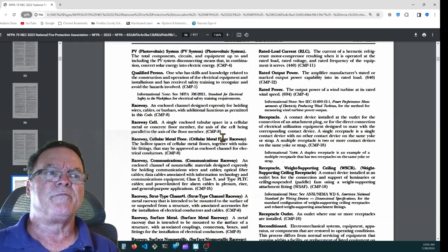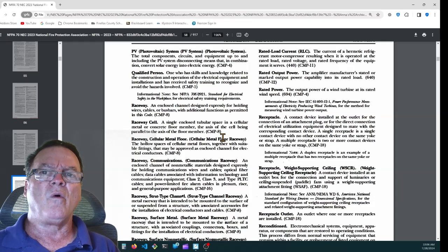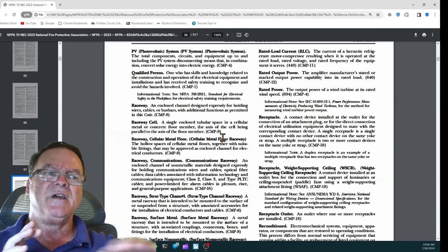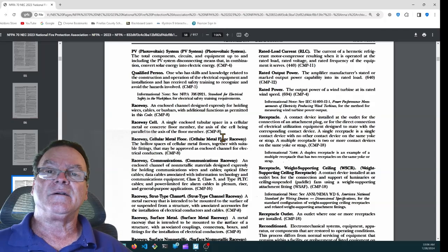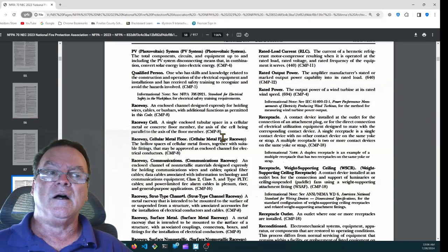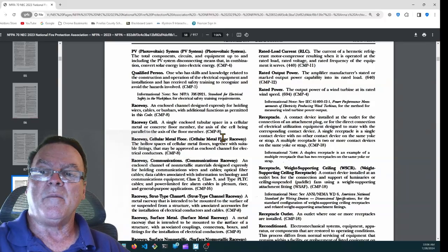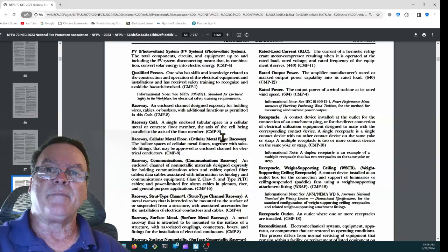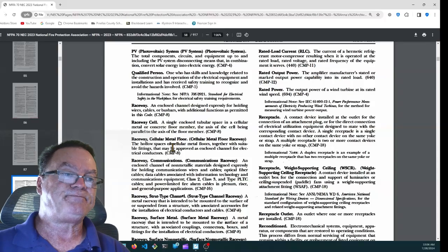So they have some preformed slabs. They can either be concrete or metal. When they pour them, they actually have these channels, these openings in them. It makes them lighter, doesn't necessarily take away too much of the strength of the preformed slab, but it makes them lighter for transportation. So they're made somewhere else, and they are moved to the job usually on a flatbed truck, moved around with a crane. And you can use one of those channels as a raceway.